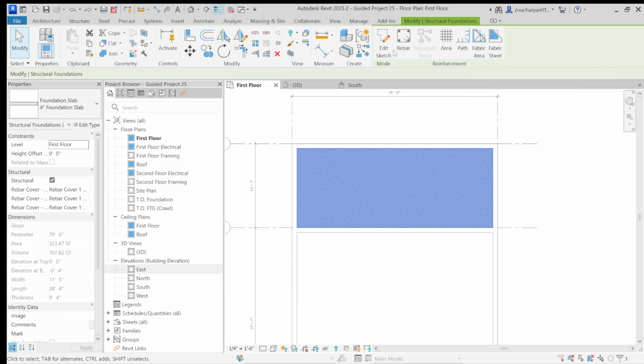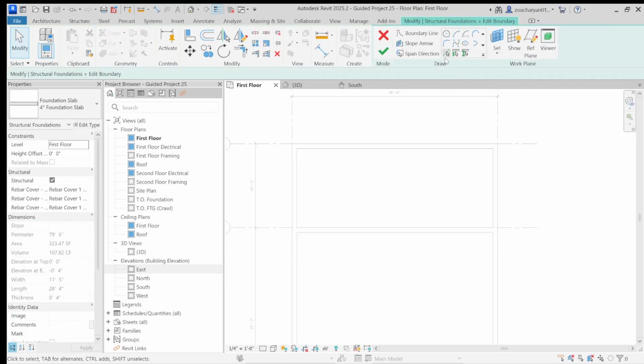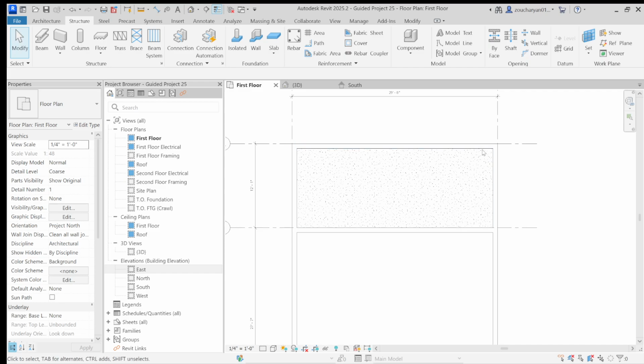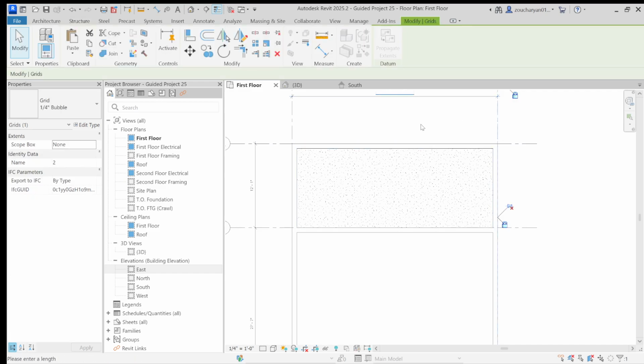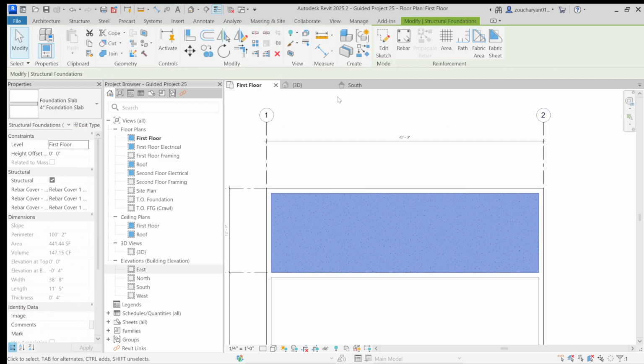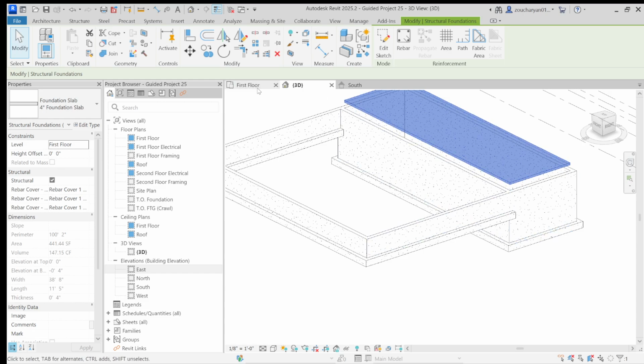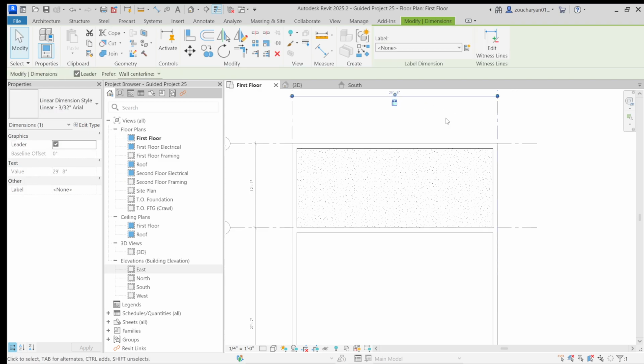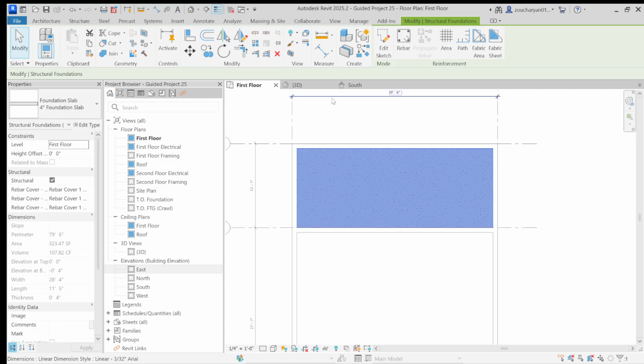Now, instead, when I make this with pick lines, lock, and I lock it onto those surfaces, TR for the trim tool. If I come in here and I unpin, unlock, and change it to 40 foot, it moves with it. Perfect. Okay. You guys don't need to do that. I would rather you leave this pinned. I would rather you leave this dimension locked. But lock them into place so that if things shift, it shifts in the correct way with it.